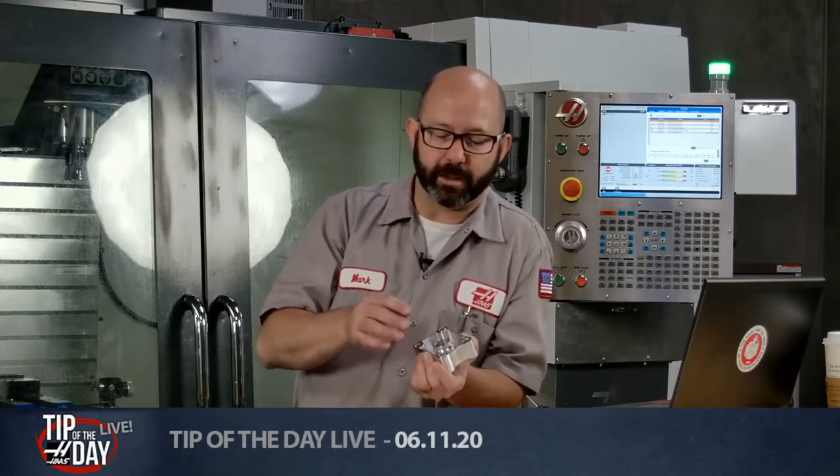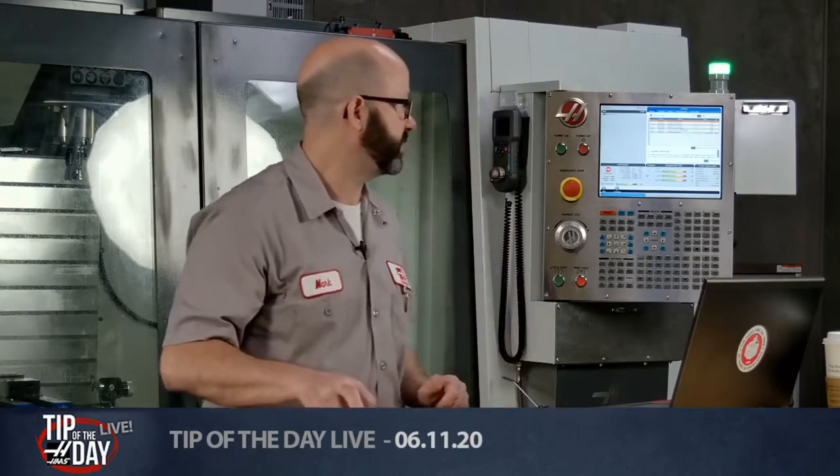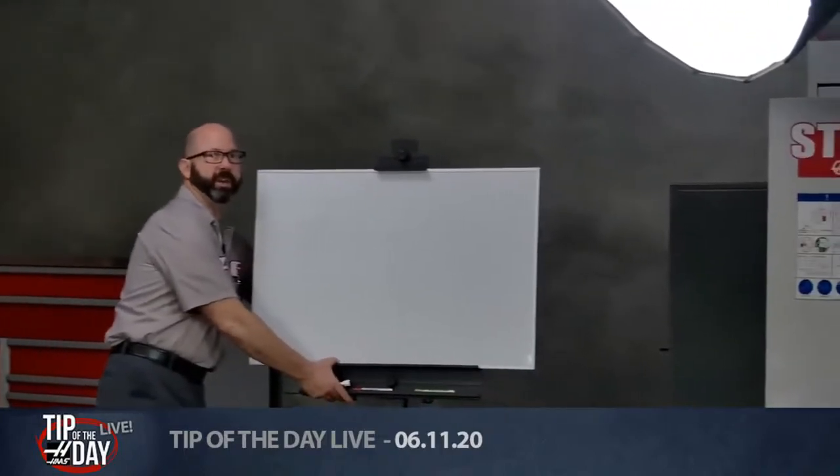If you're machining out a pocket that has no bosses, no islands in it to avoid, then that's it. You just define your perimeter, and you're done. If you have a boss in the middle, you have to get used to how the G150 cycle works. Essentially, I don't know if you can see this. It's really easy. We should do a video on this.